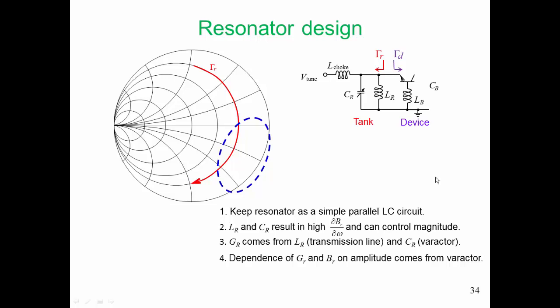And because it is a diode, it will have a finite series resistance, and that is the primary source of that conductance. A secondary source of that conductance, and it could be the major source in some situations, occurs when the Varactor conducts current. Ideally, it's a reverse bias p-n junction diode, but this Varactor diode is part of a resonator network, and there will be a large RF swing across it.